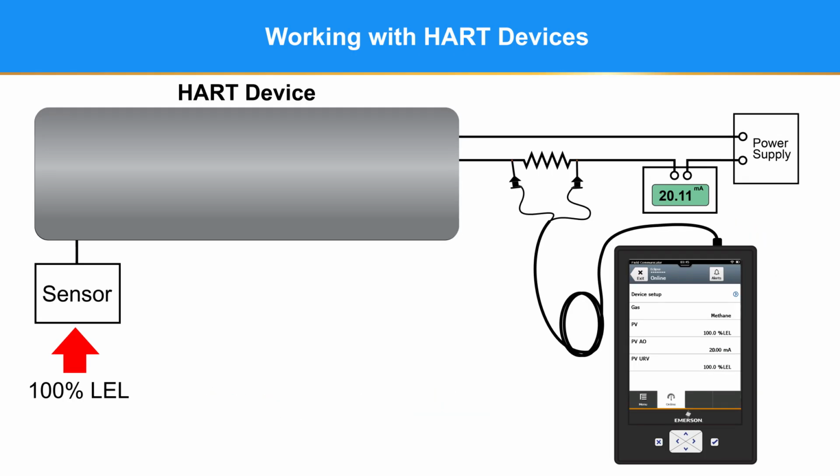Now a quick practical. What needs to be done here? First, check the calibration, as if it is not correct, the output will not be correct. That looks good. Now check the analog output. Here is the problem. If you are sure the milliamp meter is good, a D to A trim will fix this. Now on to the last topic, Det-Tronics HART documentation.